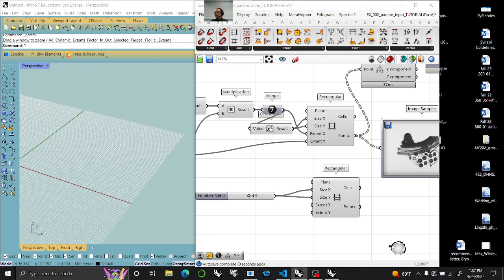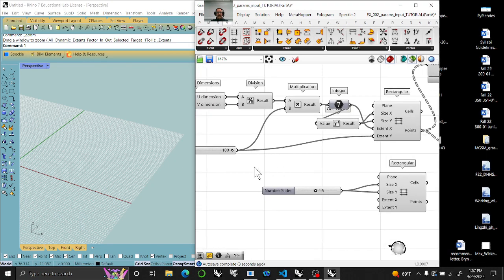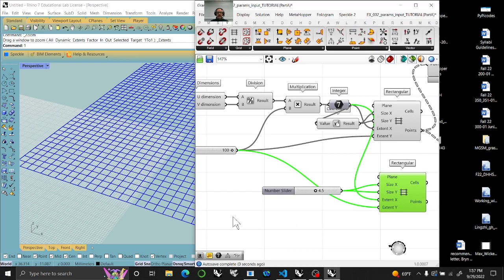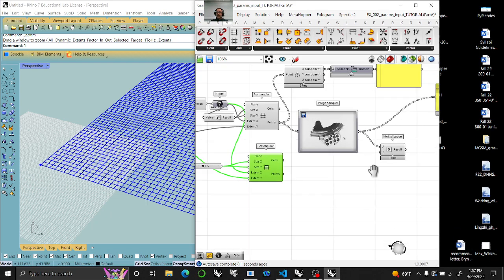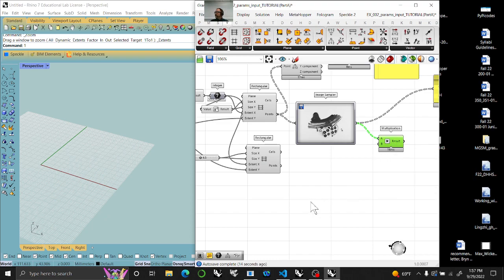I am going to keep the scale the same from the 100 scale in the x extends, and then I'm also going to grab that in the x extends here to get this grid. And then with that grid, I'll show you exactly where we go. This is kind of nice. This grid down here, I'm going to go back into my multiplier here, and I'm going to set up a moving of points. So I'm actually going to move this in a negative direction. I'm going to move this negative 20 to 20, depending on which way I want to move it in the z direction. I'm going to use a multiplier on that.